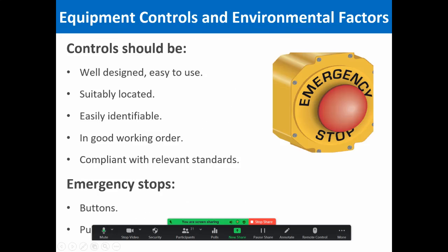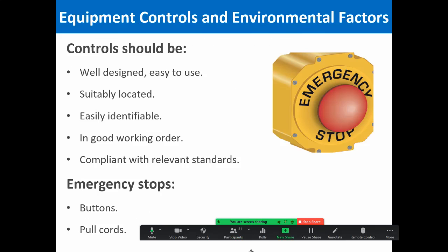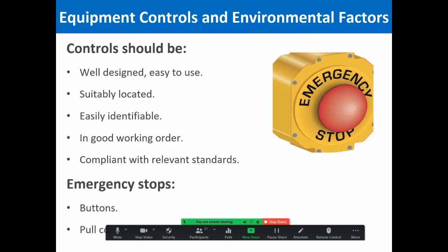Equipment controls and environmental factors. The controls should be well designed, easy to use, suitably located, easily identifiable. They should be in good working order. Also, we need to make sure they are compliant with relevant standards, and emergency stop buttons, pull cords, they must be located in suitable positions as well.